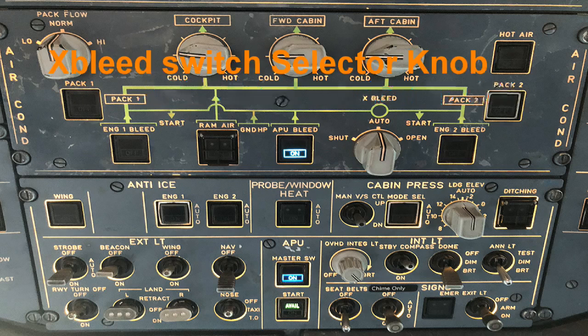Now your cross bleed selector, because there's a cross bleed system. The cross bleed selector has an auto position, an open position, and what's called shut. If the selector is in the shut position, then the motor 2 closes that cross bleed valve. Then on the bleed page of the SD, there's going to be a green cross bleed valve symbol that shows in the closed position. So closed, you're going to see it in green when it's in a shut position.